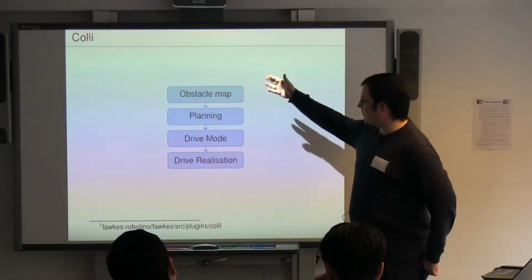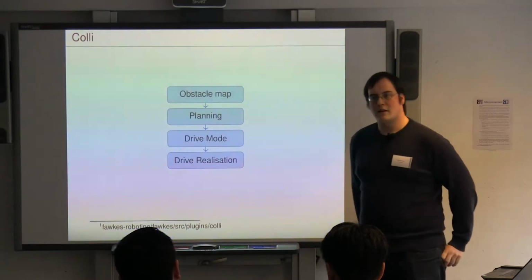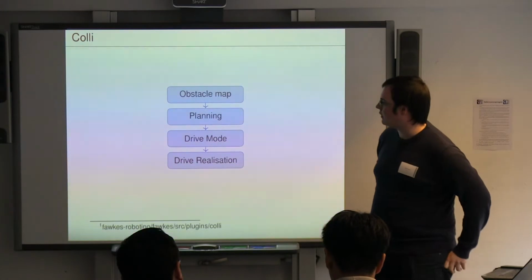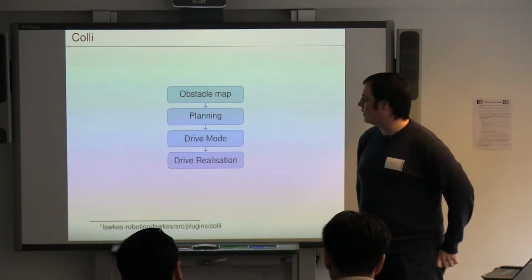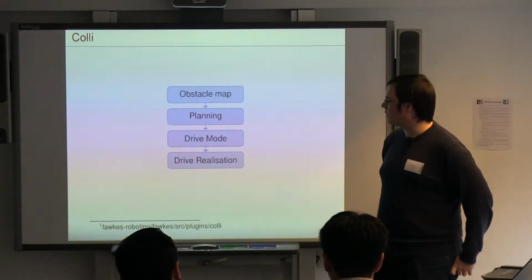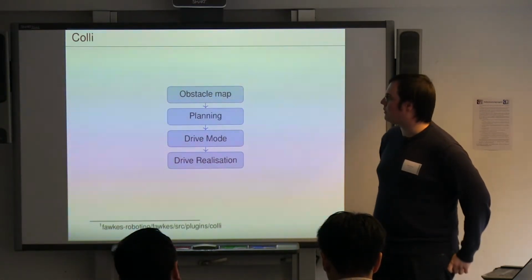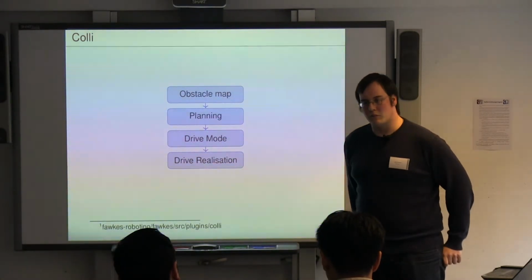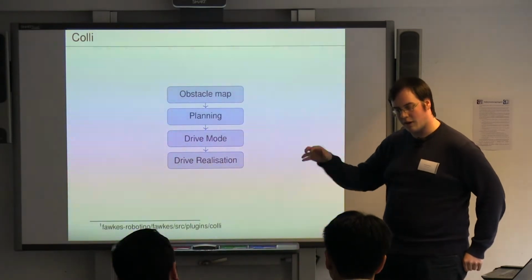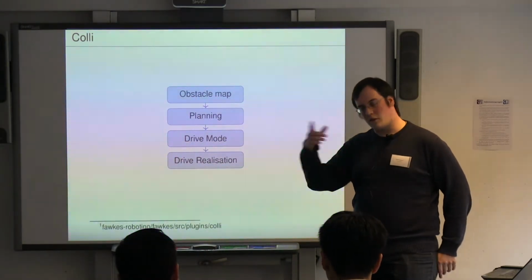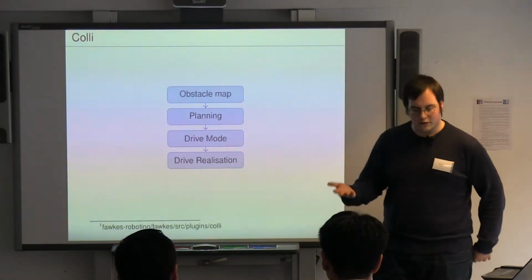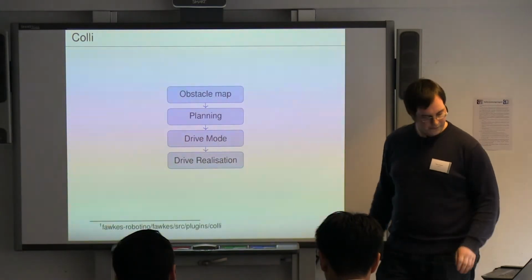That is the workflow of our local planner, which is called with 10 hertz periodically, and I think one thing that's very special about this planner is that it's mostly stateless. So if it plans a path during one step, and then it's called after 0.1 seconds again, it calculates a totally new path.